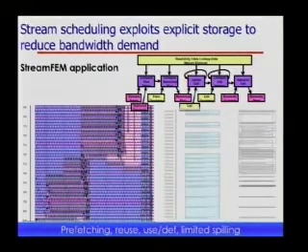Yeah, question? Would you recommend relying on this static schedule for correctness or only for efficiency? So it's guaranteed to be correct, but the reason why we're doing it is for efficiency. Because it's much more efficient to have a compiler solve the combinatorial optimization problem of how to pack your on-chip memory in time and space.